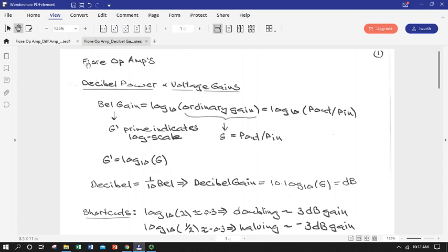Quite often we're going to be looking with operational amplifiers at huge ranges of gain, going from no gain, just unity gain, or even an attenuation, maybe negative gain, gain less than 1 on a ratio, to something several orders of magnitude higher. Quite often the circuits we'll be looking at are going to vary their gain with frequency input. So the same circuit will give a vastly different gain depending on what the frequency of our input signal is. So we need a way of expressing gain over huge spans of orders of magnitude changes. And that's what the decibel scale is great for.